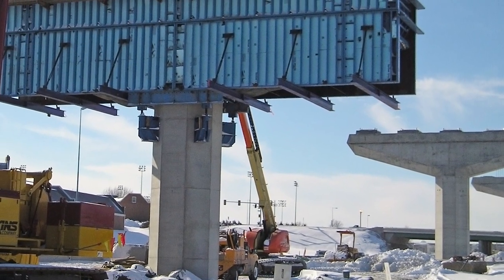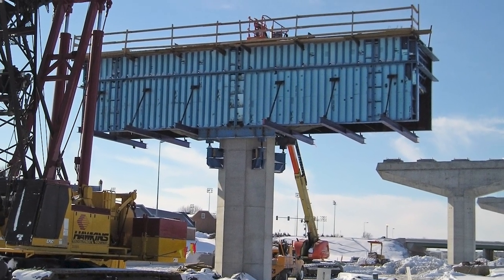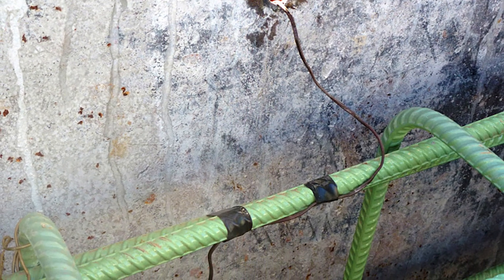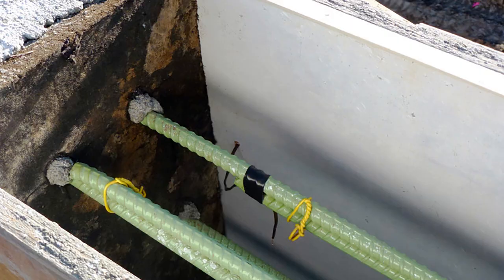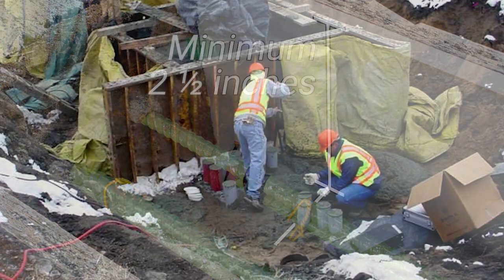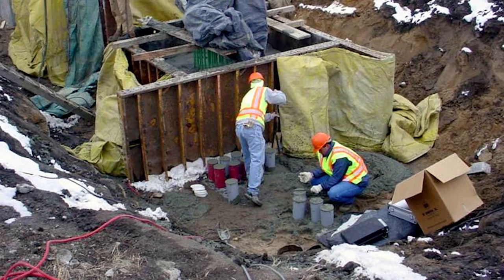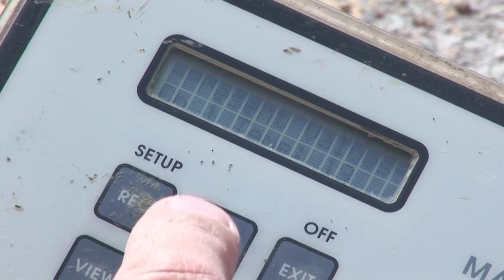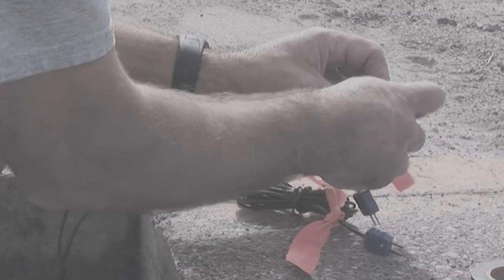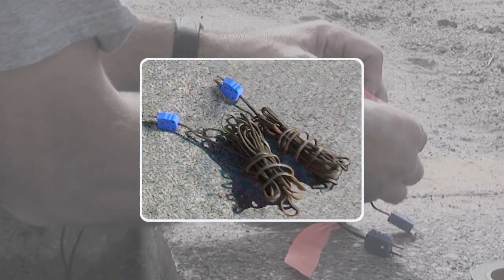The setup and monitoring procedures for structures are similar to those for slip-form paving operations. It is recommended using a minimum of 2 thermocouple wires placed in the structure, with a minimum concrete coverage of 2½ inches. The placement of the wires into the structure is at the discretion of the project engineer. Test the wires for conductivity by taking a temperature reading with the monitoring device. Once the wires are tested, it is recommended to take measures to protect the wires and connectors from being disturbed.